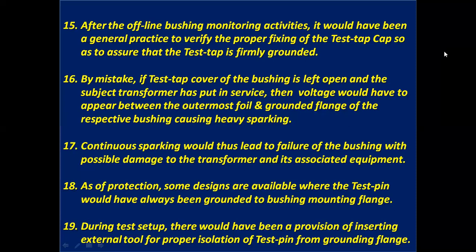As a protection, some designs are available where the test pin is always grounded to the bushing mounting flange. In that case, during test setup, there is a provision of inserting an external tool for proper isolation of the test pin from the grounding flange.